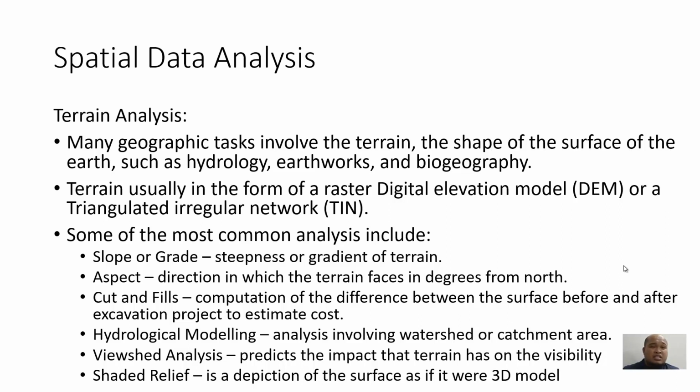Whether the steepness is still stable, whether the steepness is suitable for vehicles to pass through, whether the steepness is suitable for a rescue team to go through the terrain. So the gradient can be presented usually in terms of percentage and degrees, right? But most people use degrees rather than percentage.